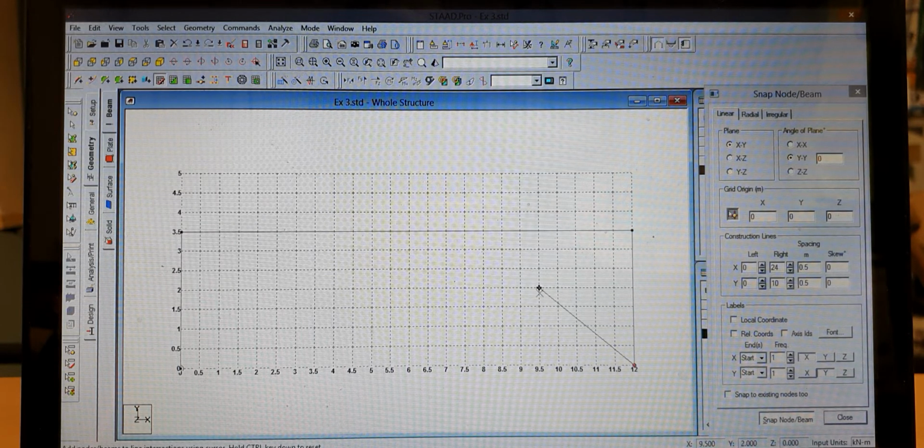So next I'm going to click this point, but I don't want this line to be created. So therefore again you need to hold control button and click this point. So we don't have a line here, we have a point only, and then click this. When you click this point, the STAAD.Pro will divide this line into 2 at this position. Now you can stop.